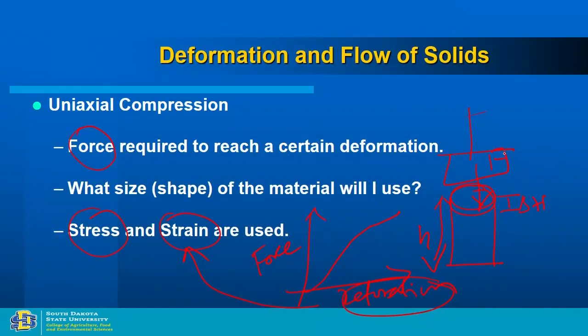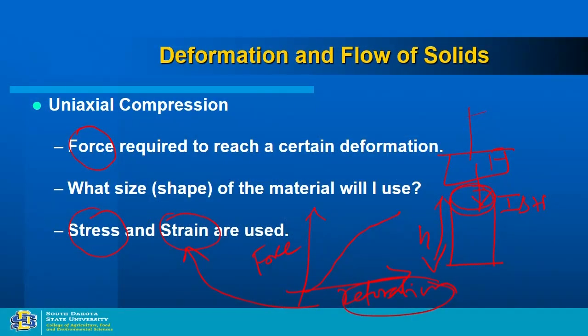For small grains, if you have a load cell which can take a small amount of force, you can still test the actual grain as it is, but otherwise you won't be able to do that. Another test you can do is to take it in a cylindrical cup and do a shear test. You can attach some type of plate and then shear the sample. That is similar to a compression test, but you are not really compressing it, you are just shearing it. But you will still collect similar force deformation data. So, very good point. Other questions?